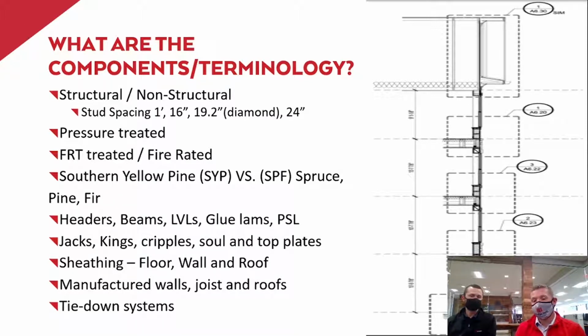So if your carpenter is utilizing 2x4s for a PSL, say it's a 4x4 PSL, nominally 3.5 by 3.5, your carpenter puts in three 2x4s, giving you 4.5. May seem like it's equal, should be fine. It's not. Those studs are not rated for the same capacity as that PSL. Where they're using three studs, it's possible that they may have to use eight studs, impacting your electrical locations for outlets, impacting where you can put hose bibs out the side of your building. There's a lot of ramifications to not following the plan.